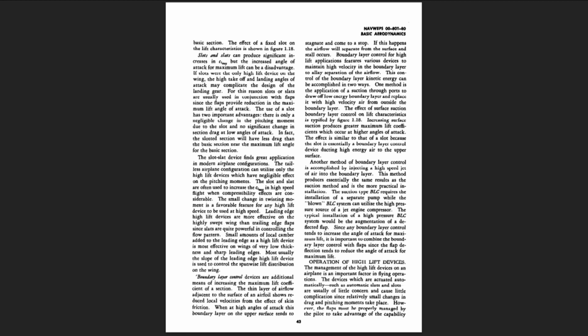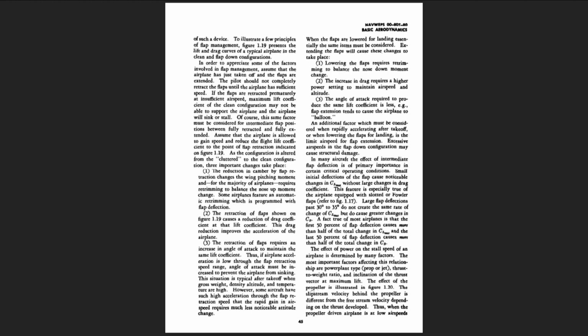Operation of high lift devices. The management of the high lift devices on an airplane is an important factor in flying operations. The devices which are actuated automatically, such as automatic slats and slots, are usually of little concern and cause little complication, since relatively small changes in drag and pitching moments take place. However, the flaps must be properly managed by the pilot to take advantage of the capability of such a device.